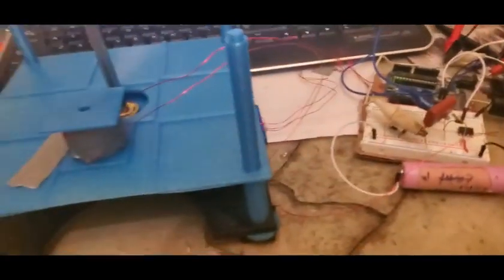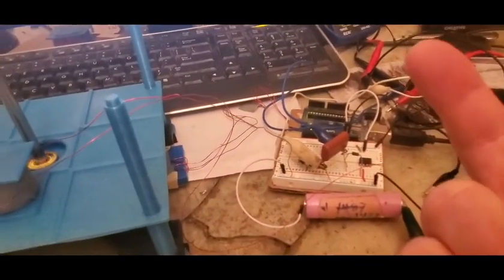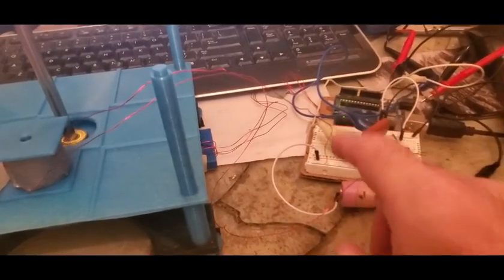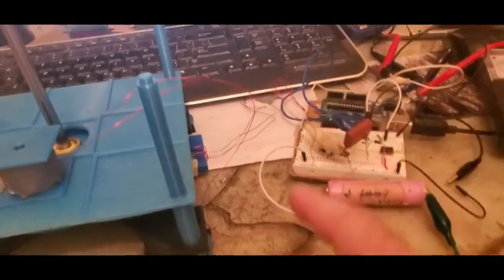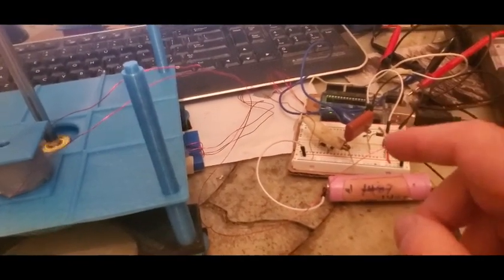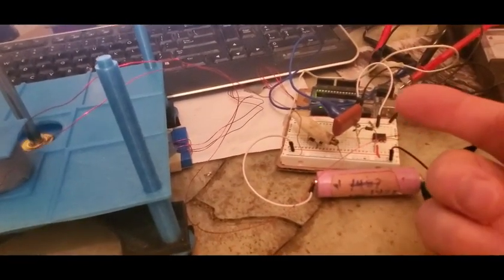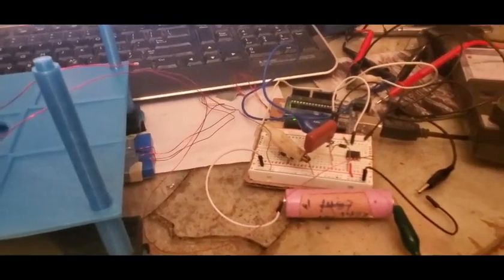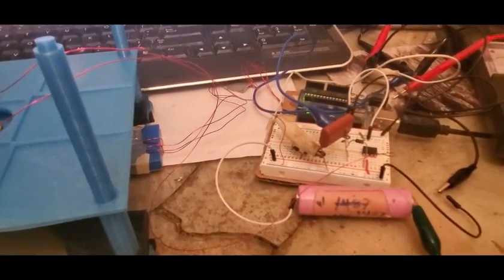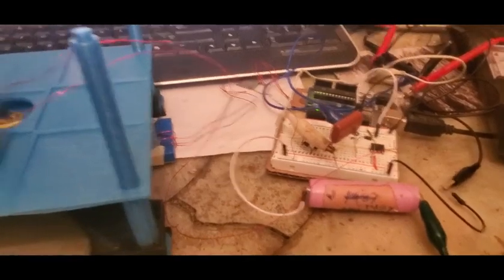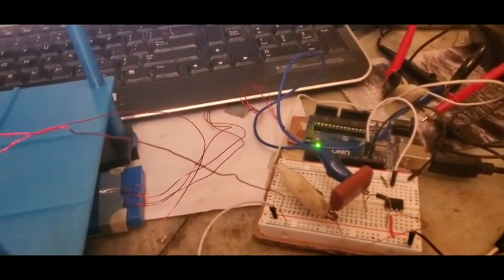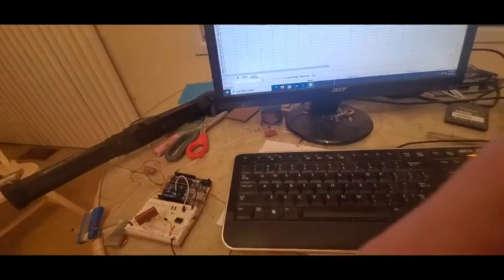It's just, if you use a monopole, use a single diode rectification. If you're using bipolar, you need the full wave bridge rectifier both to catch the negative, and also the single diode would just be a short on half of your cycle. So we can confirm that when we go to bipolar. But last thing, let's put this in a spreadsheet. This is kind of interesting.